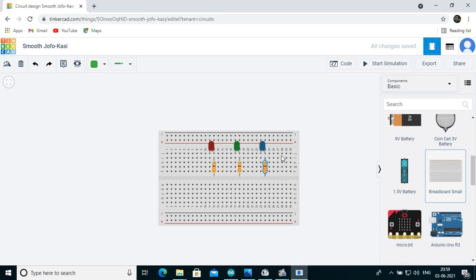If you connect the LED here and your resistor here also, it will work, because all these holes are connected vertically. And here all are connected in the horizontal form, like all holes are shorted with one wire. So if you connect anything here, it will all be connected together.